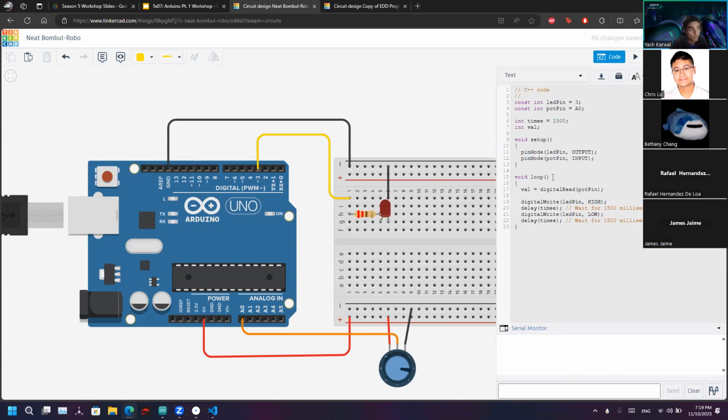You can use this. So how we're going to do this is, first in the setup, we're going to do this thing called Serial.begin. This will start the serial communication between your Arduino and whatever serial device you're going to use. And this 9600 is the baud rate, the rate at which we're listening, I think, if I remember correctly.